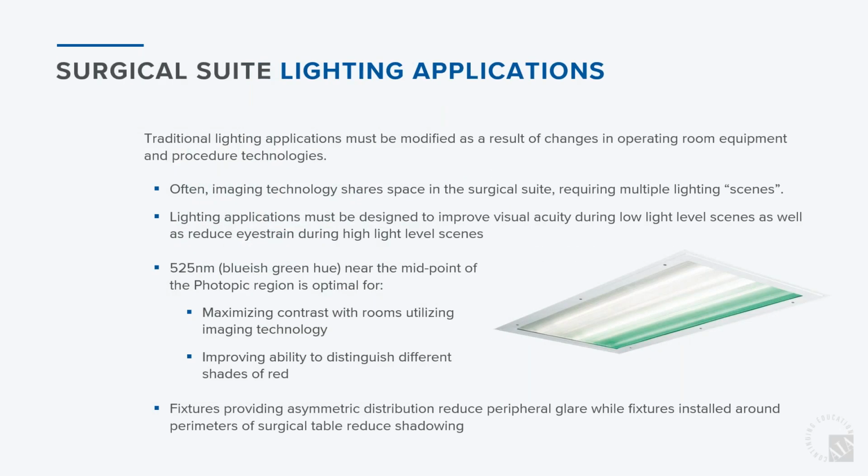So we get into these specialized rooms within a hospital setting. You think of your surgical suite lighting applications. These specialized areas require fixtures that direct light asymmetrically and contain a green source for ease of eye strain during long operations. It also distinguishes between different tissues because of varying degrees of red, such as blood. Surgical troffers nowadays actually carry a green circuit on them, much like this picture you're seeing here. And so you have white and green circuits that you can switch separately.